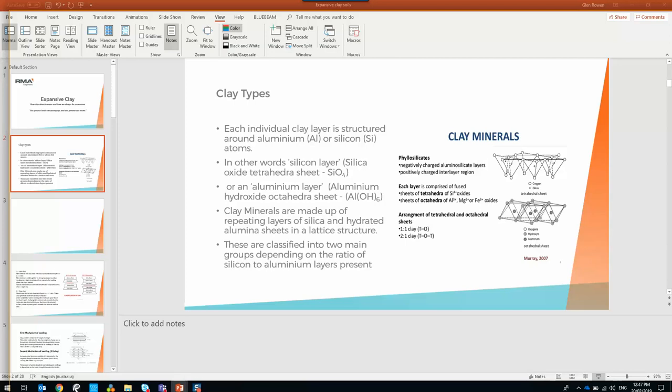So typically that one where that shed was had about 1 metre of fill, so we still suspended it. But on the other end of the site, the admin and lab buildings were on about 2.5 metres of fill, so we put a stiff raft on them. So it's just a matter of looking at how much fill you've got and which options you need.